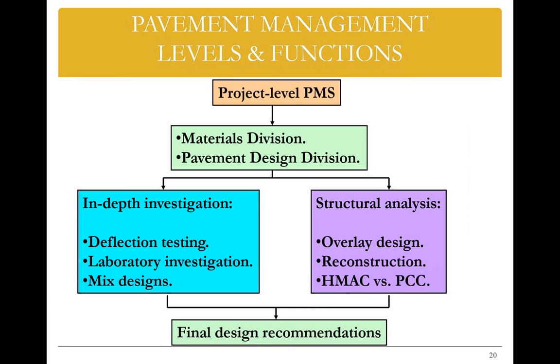I would take a sample or a core, go to the lab, and apply some tension or compression tests to know the performance of that road. I will also need to replicate the mix design. Sometimes, once we do the lab investigation on a certain sample, I would heat it up and try to replicate the mix design and see what went wrong regarding any parameter in the mix design.